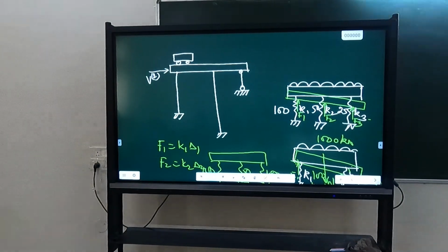And the reason is the P delta effect, because of the axial force. P delta will be there in any case, even if the hinges are in the beam, if the displacement is occurring, P delta will occur. So why we do not want it in the column? I have repeated this several times. Because of the axial force, ductility will be less. And if the ductility is less, in bridge also, the axial force will reduce the ductility. If ductility is less, what will happen to the response reduction factor?